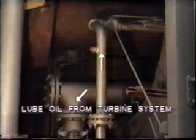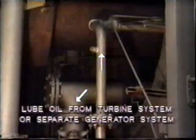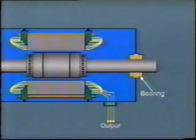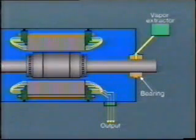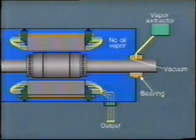Pressurized lube oil may be provided from the turbine lube oil system, or in some cases a separate generator lube oil pumping system is installed. On many units, the top of each journal bearing is vented through a vapor extractor. This creates a slight vacuum inside the bearing and so prevents any oil vapor from accumulating inside the generator housing.